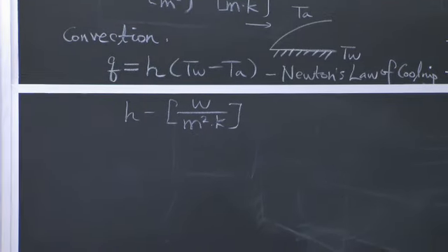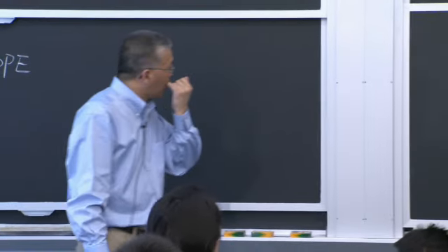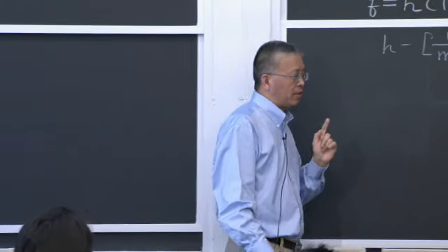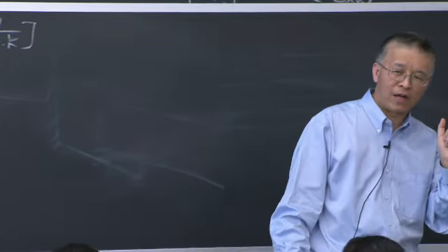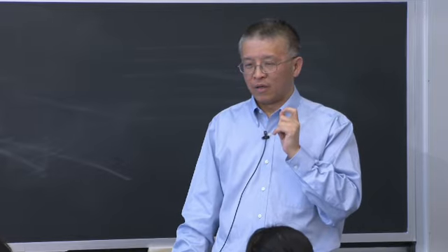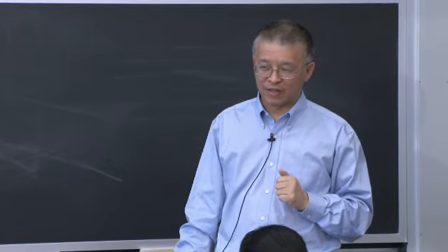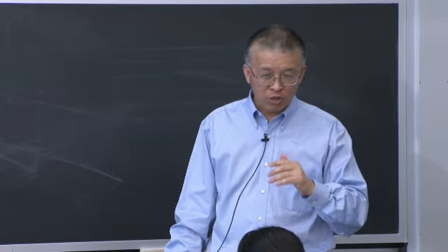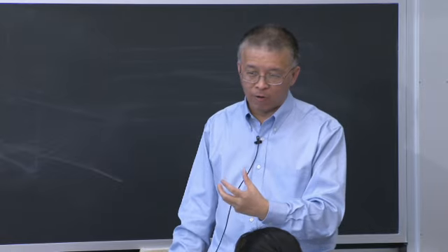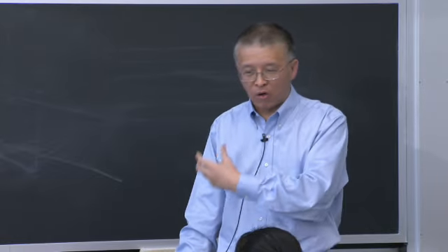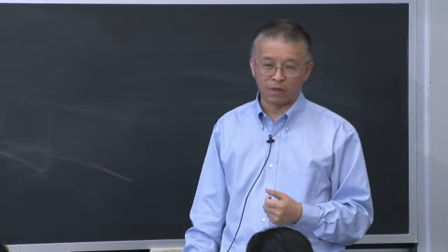If the case is complicated, you go do the experiment, right? And one thing I want to remind you: if you do fluids problems or heat transfer convection, on the wall you often invoke a condition. What is that condition? No slip, right? So the velocity of the molecule is equal to the velocity of the wall, and the temperature is equal to the temperature of the wall.